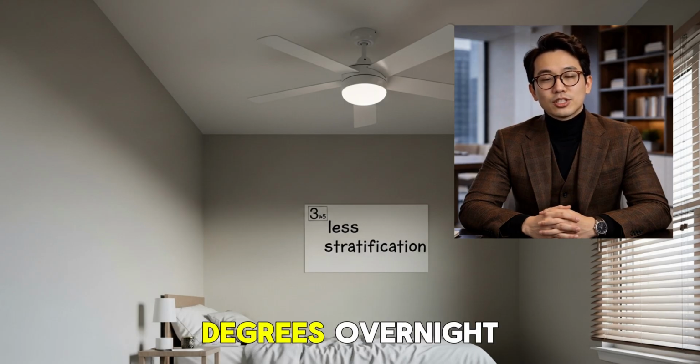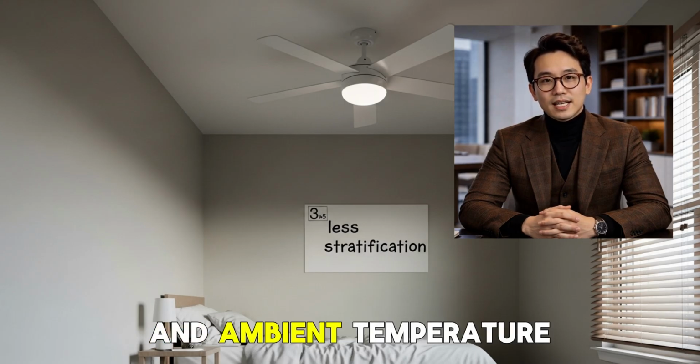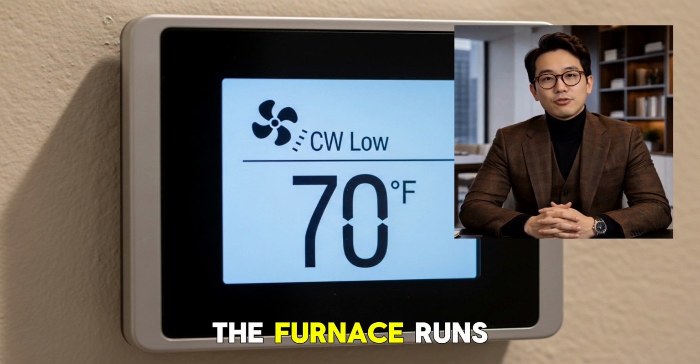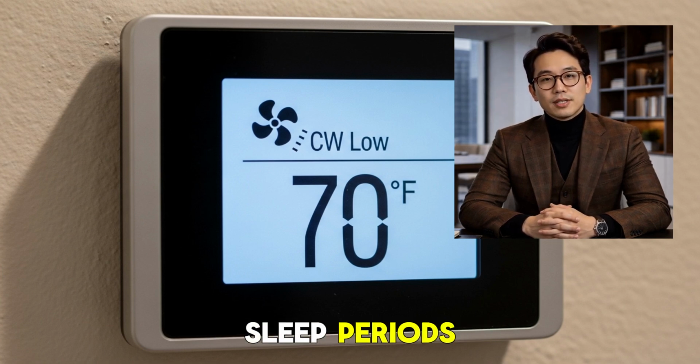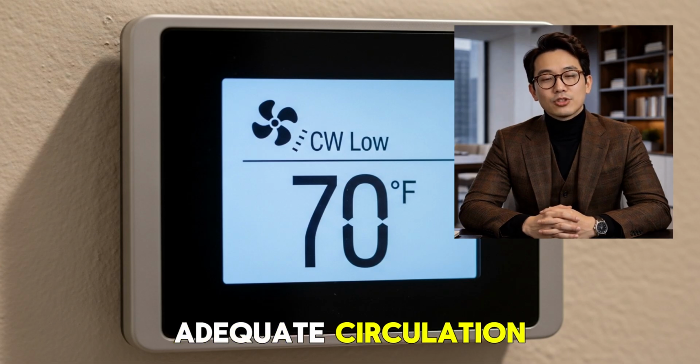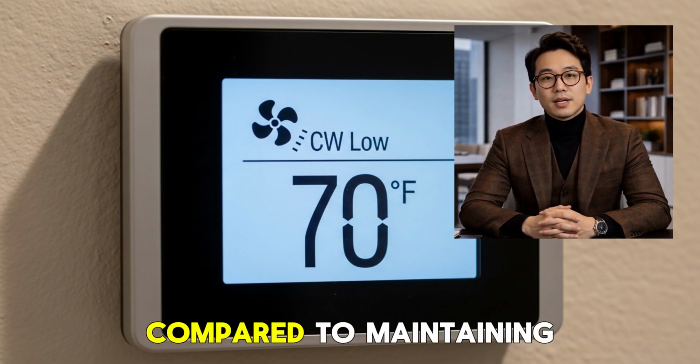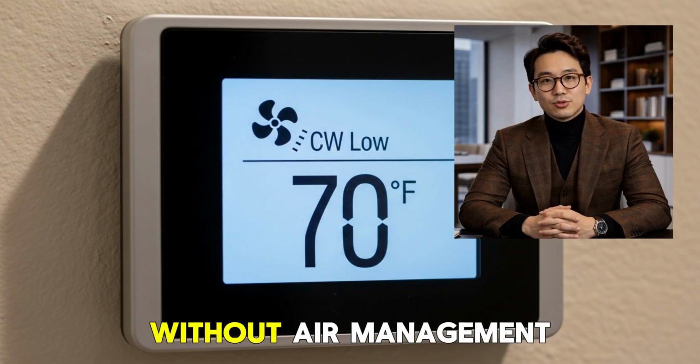Drop to 62 degrees overnight when occupants are under blankets and ambient temperature matters less. Return to 68 1 hour before waking. The furnace runs minimally during 8-hour sleep periods. Ceiling fans maintain adequate circulation during occupied hours. Total heating costs drop 30 to 40% compared to maintaining constant 72-degree settings without air management.